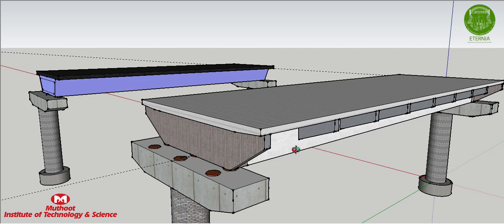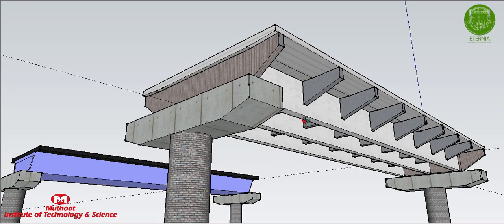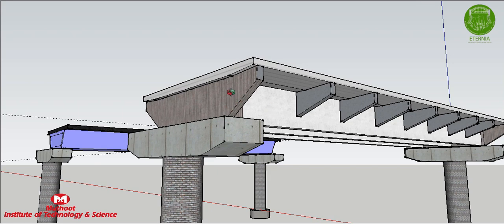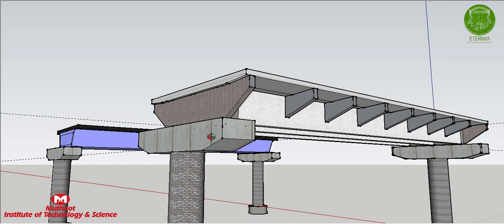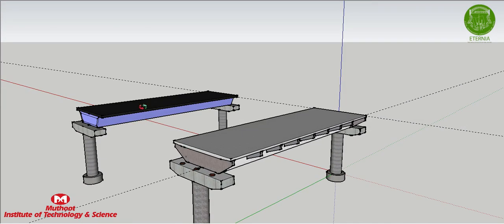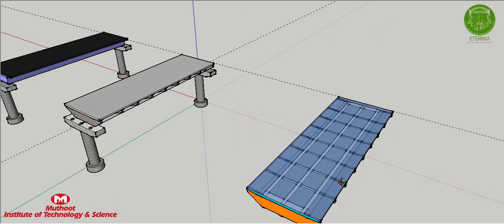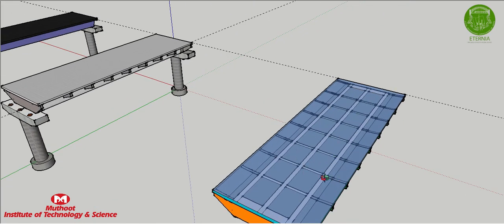These cross girders and longitudinal girders are generally Euler-Bernoulli beams. And when we think about components like the diaphragm wall, the abutment cap, or even the pile cap, they are deep beams. To get a better view of this I girder bridge, I have made this top portion, which is basically the deck slab, transparent.